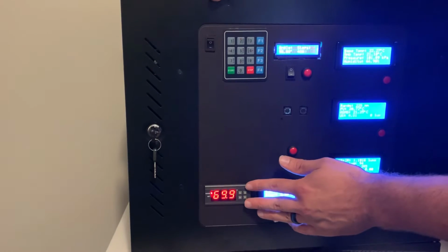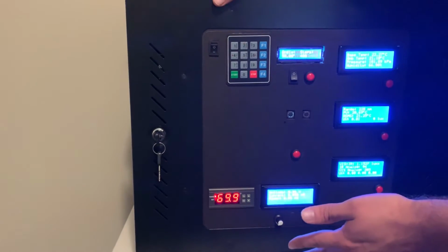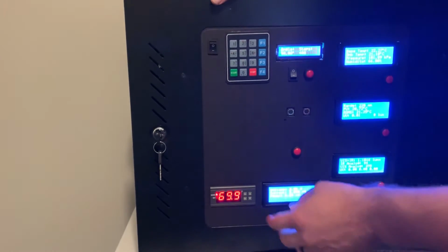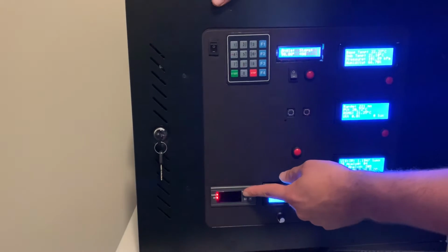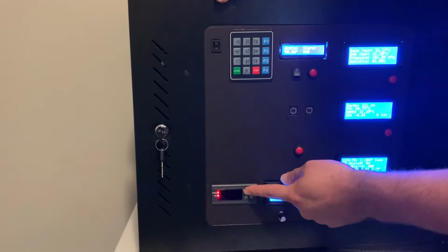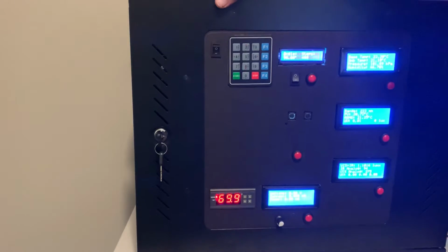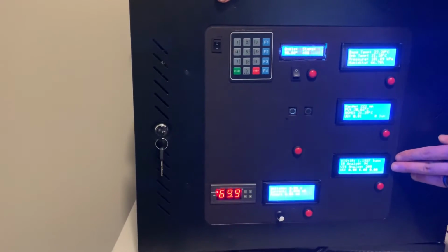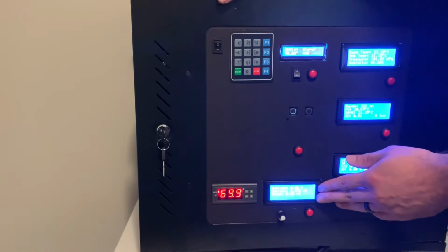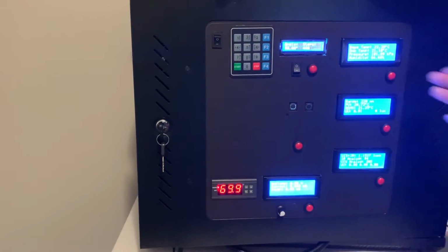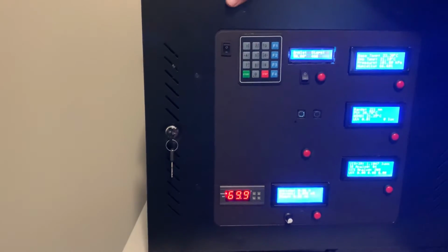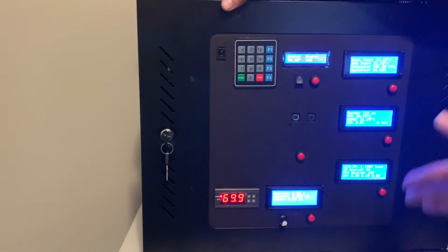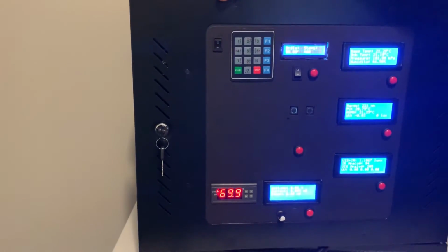This right here is my temperature controller. Unfortunately, it's in degrees Fahrenheit, but I can do some basic math and translate that. I can set it through an array of temperatures to control those hot spots that I was talking about and measure the difference. And between my spectrum calibration and response and my photocurrent measurements, I can log a myriad of data, both environmental and what the spectrum response is to the photovoltaic output.